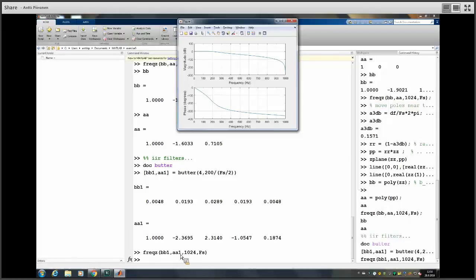Oops. A little bit different. Okay, there we go. I cannot quite see the ripple. Okay, there we go. So on the passband it has 2 decibel ripple, so variation of the passband response. Compared to the previous, this actually has a better transition bandwidth. Okay, you cannot really see it from here, but it has.